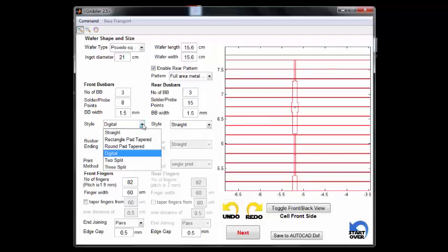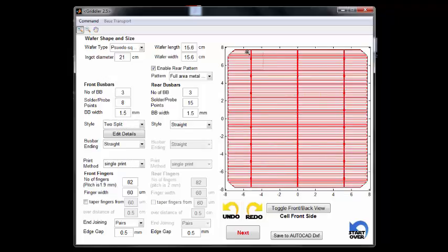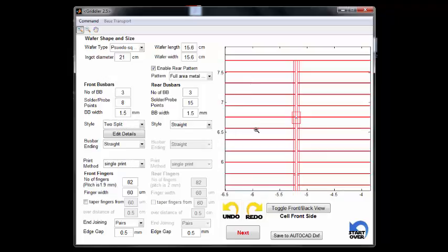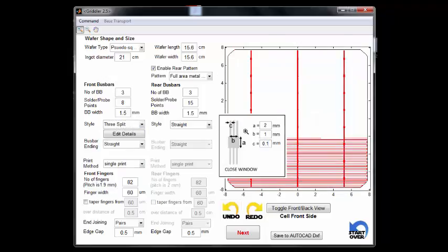You may have also seen segmented bus bars, so these are described by either what we call two-split, in which case the bus bar segment looks like the following, and here is repeated 8 times. You can also do 3-split, and then there will be 3 of these connecting sections. So maybe we reduce the width of these connecting sections a little bit.